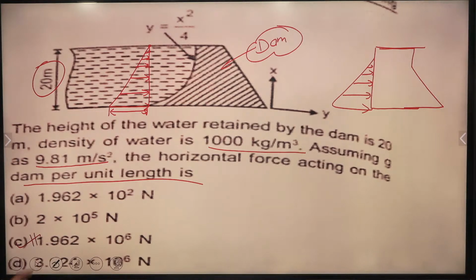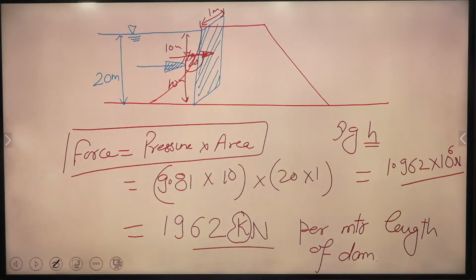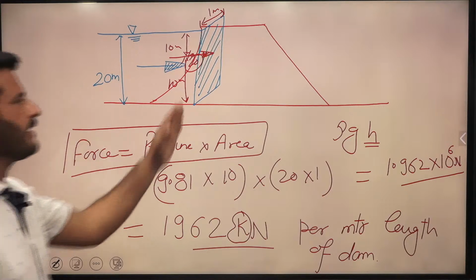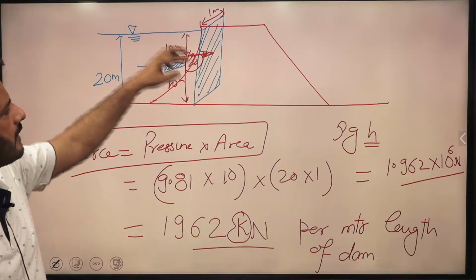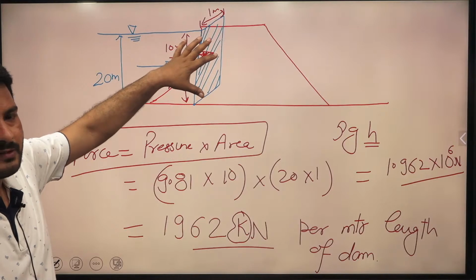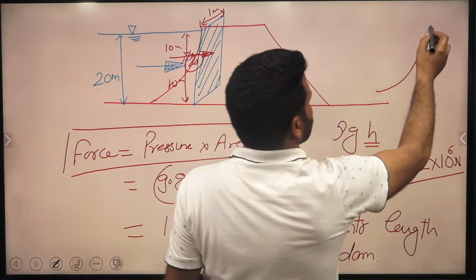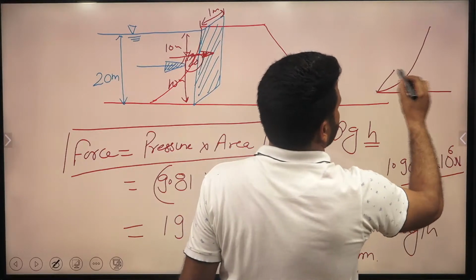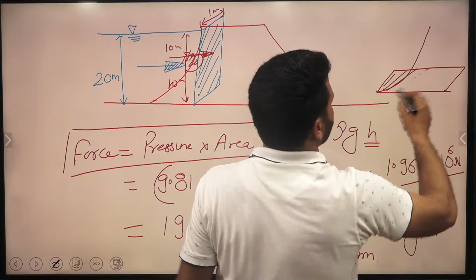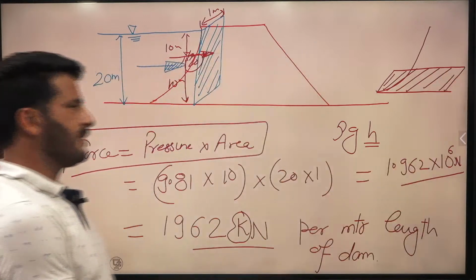So it is a very simple question, we just consider the curved surface a little. Whenever we are considering a curved surface, how do we calculate the horizontal force on it? Just multiply the pressure by the projected area in the vertical plane. If you are going to calculate the vertical force, that is the weight of the water we are considering on this curved part, so we just multiply the pressure by this horizontal area. Or even you can consider the weight of the water on this column.